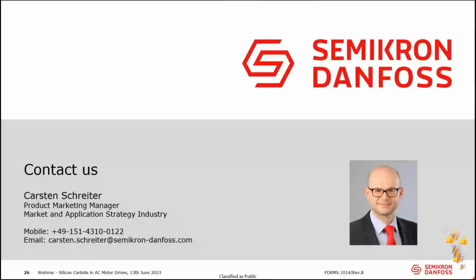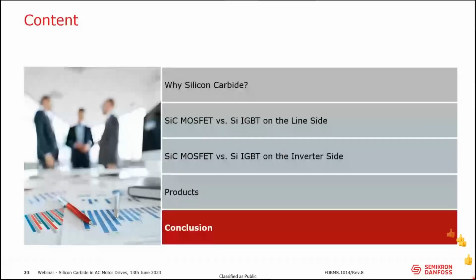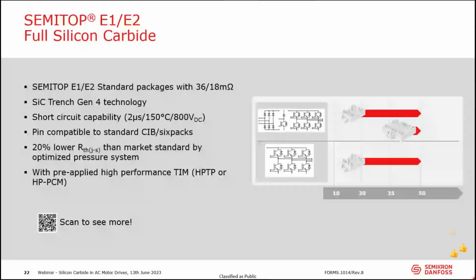So with silicon carbide, what are the voltage ratings? What's the highest voltage rating that we have for these devices? At the minute, what we have is 1,200 volt devices. That's also what you could see on this slide here, where I had the module. It's not even written, sorry for that, but those are for 1,200 volt.